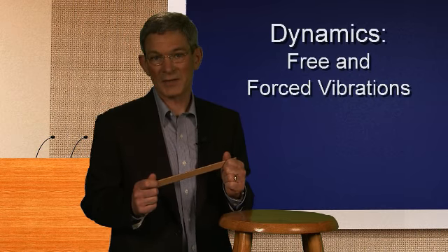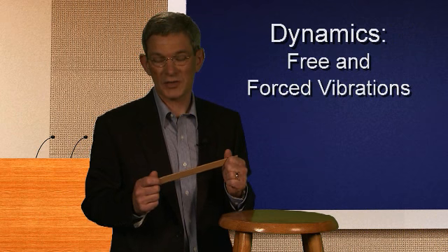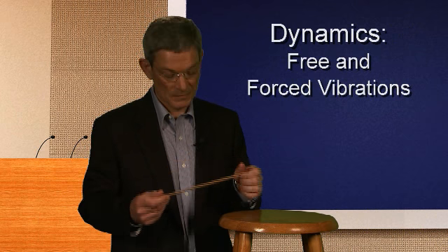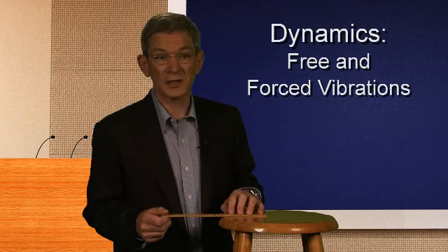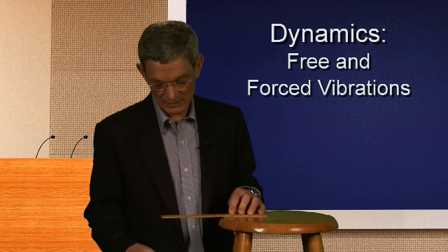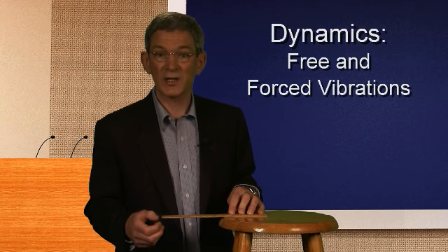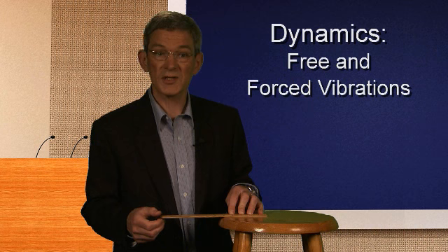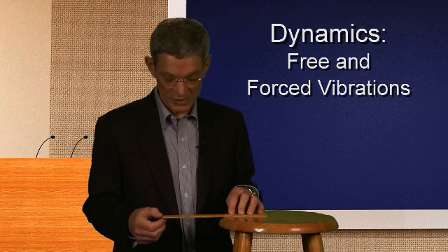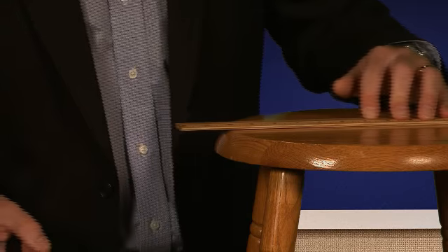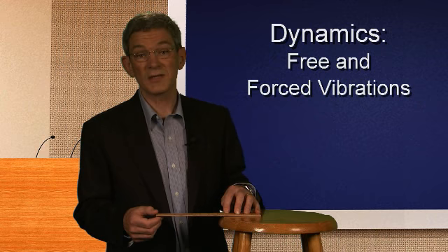So our next example is for dynamics courses. The topic is free and forced vibrations. And we suggest you take a ruler into class, clamp it down onto the bench and flick the free end. So you get a nice noise like that. You can also slide it up the bench so the pitch changes. And the frequency will go up.